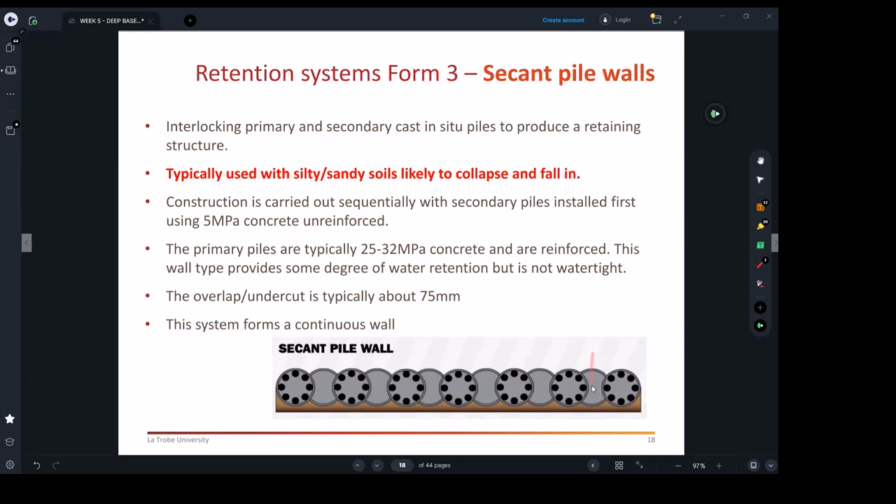You don't do them all in one go, because obviously if you do the whole line, they're gonna get hard maybe by the next day. In the same day, you have to plan for pouring maybe 3, right? And in the same day, while it's still kind of excavatable, you're gonna come and excavate these 2, the reinforced ones, because you're gonna go through the concrete you just placed, and you will place the required reinforcement, and then all that section will be done.